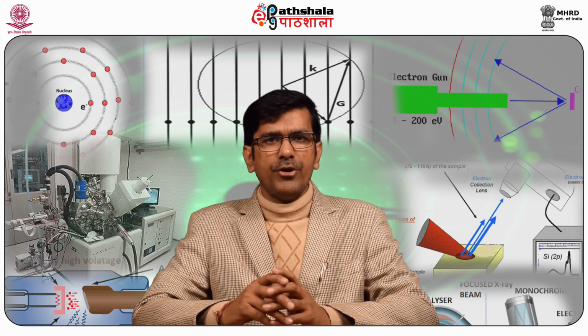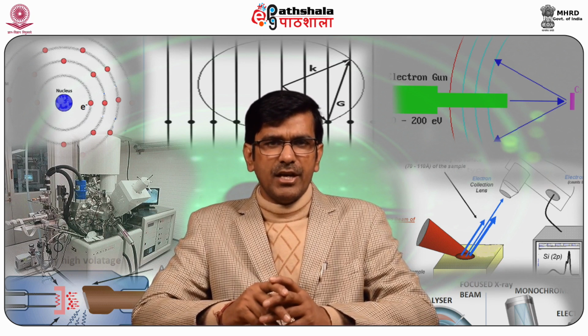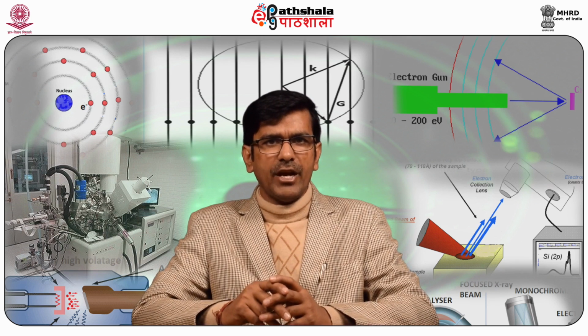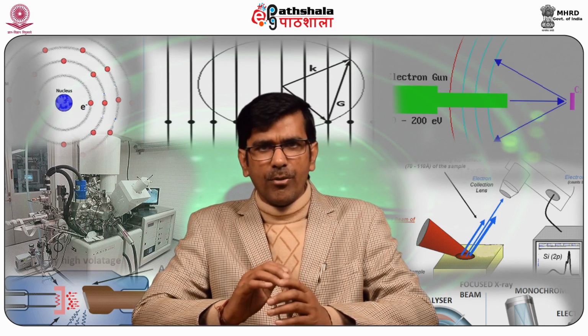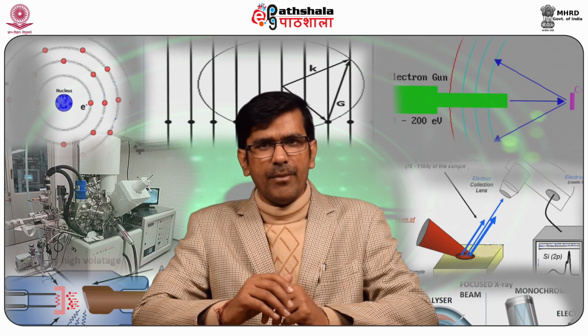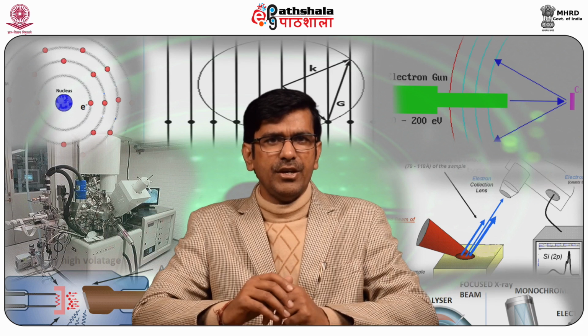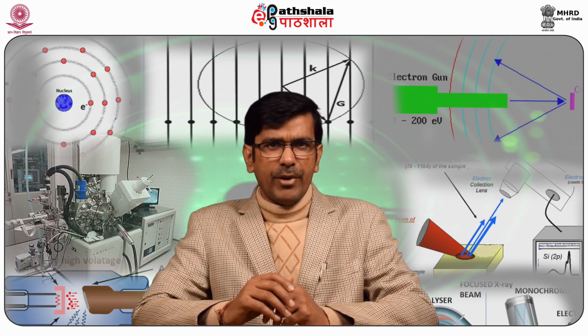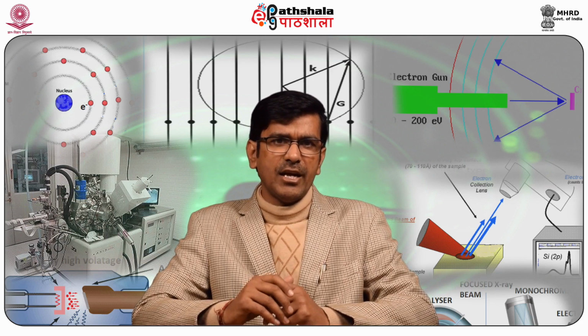Now, the third point is secondary ion mapping. It measures the lateral distribution of elements and molecules on the surface of the sample. In order to obtain a SIMS map, a highly focused primary ion beam is scanned in a raster pattern across the surface of the sample, and the secondary ions are analyzed on the selected surface area.